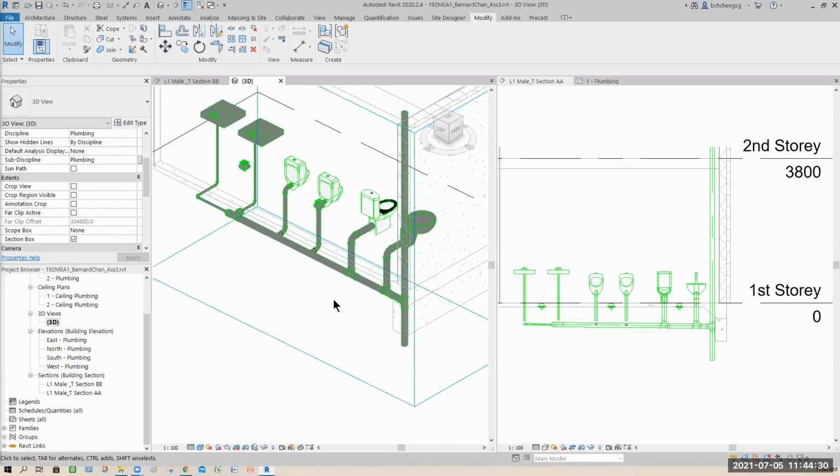That's why you can see in this toilet design, they only have two. But you see the toilet in BCA Academy Tower, I think there are 4 to 5 cubicles, right? In BCA, only the first two connect to the main pipe. The rest will connect separately to this main pipe. You have to do that. This is a must, the practice, okay, when you're doing sanitary work in future.